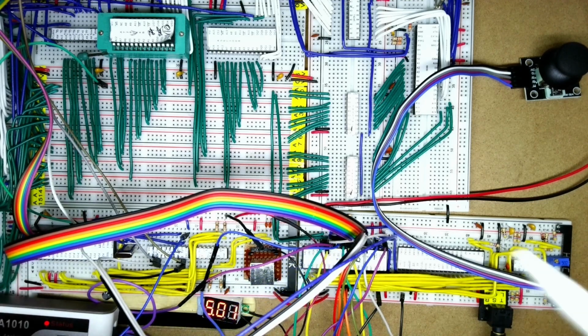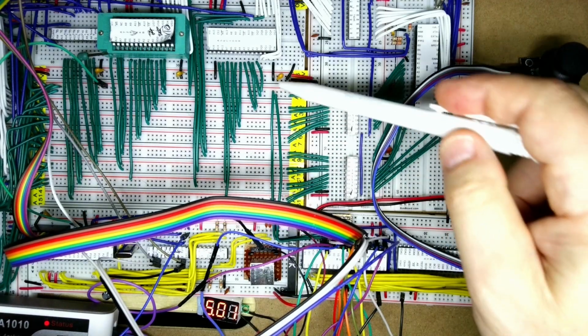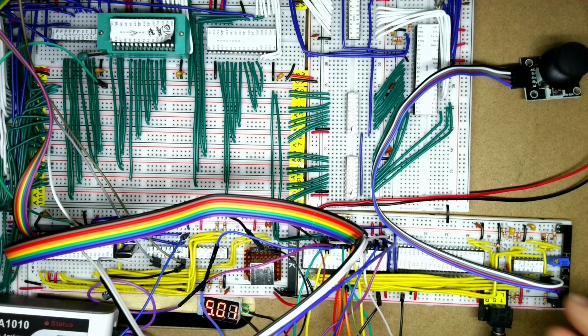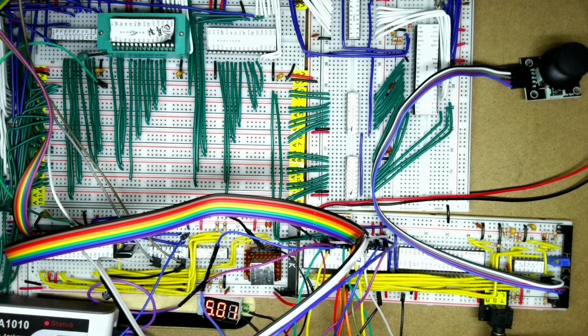I've also got the address A0 and A1 lines coming in here, and these are wired the correct way for this particular chip, unlike the keyboard PIA. And everything's all plugged in. I've also got an old set of speakers plugged into here, so hopefully if I mess up, at least I won't blow up my main speakers.